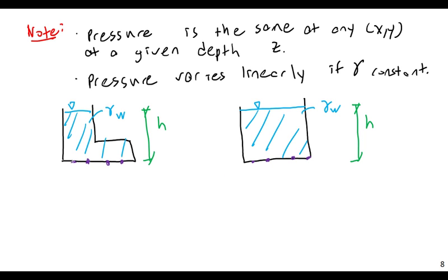at the bottom of the tanks, all of these purple dots have the same pressure. It doesn't matter that I'm going back underneath this, the toe of the boot, for lack of a better word. I'm going deeper into the fluid, and that's what's kind of weird about it, because if you look at the distance from the surface, this point is going to be a lot farther from the surface than this point here. Here you could just go straight upward. But here you'd have to go around, first left and then up, or up and around.